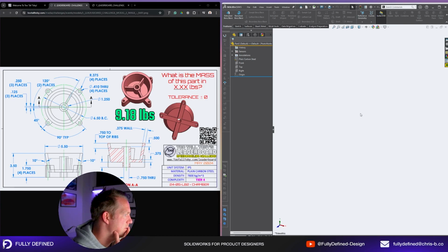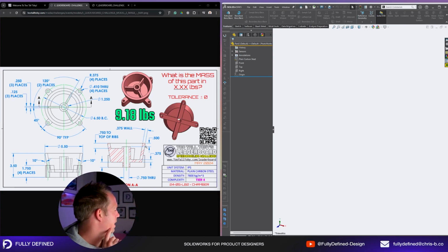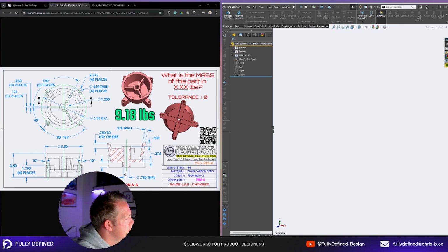We could do a revolve, and I'm thinking to do the revolve because of the wall profile. Even a revolve thin, although the revolve thin would give you an angle for this top edge at this point. So if you do a thin revolve, it will have a little face that sits up like that instead of sitting horizontal. So maybe that's not the go. You see that different wall thickness too on the outside wall and that bottom part that sticks out the bottom. Doing an extrude is not the right idea because you do the extrude with draft. It could be, but you're doing multiple steps.